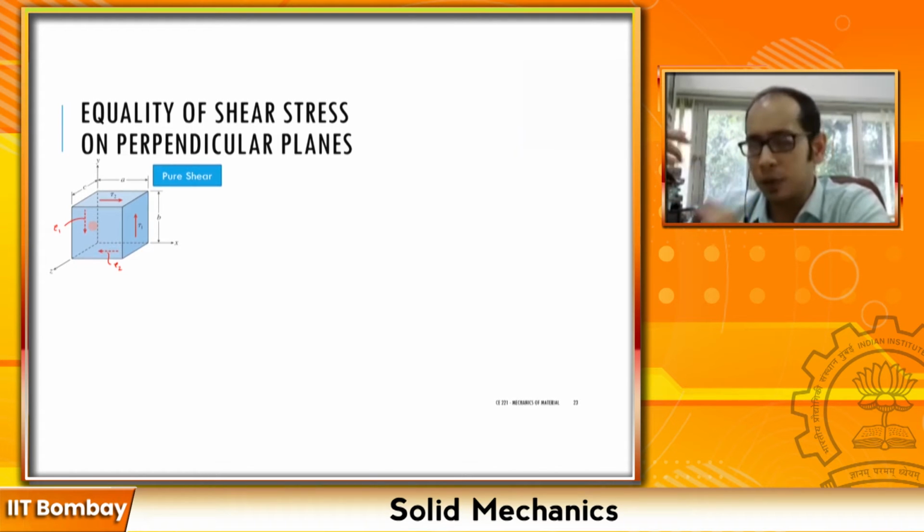So first, let's take a look at the relationship, or if there is a relationship. If this is the stress, remember for a couple, or to calculate a moment, you need the force. You cannot do it with the stress, right? So if we have this tau 2 over here and this tau 2 over here, the net force acting on this face or this face over here is going to be tau 2 times the area.